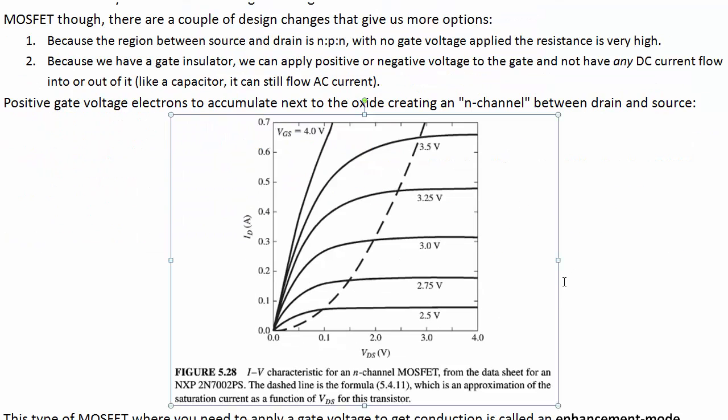Okay, so here are the characteristic curves for a MOSFET. It's exactly the same as it was for our other FET, so it's still N-channel, meaning that the lower the gate voltage, the lower a curve we go to, except that we're zoomed in, so don't let that throw you off. And as we apply more and more gate voltage, the curve goes higher.